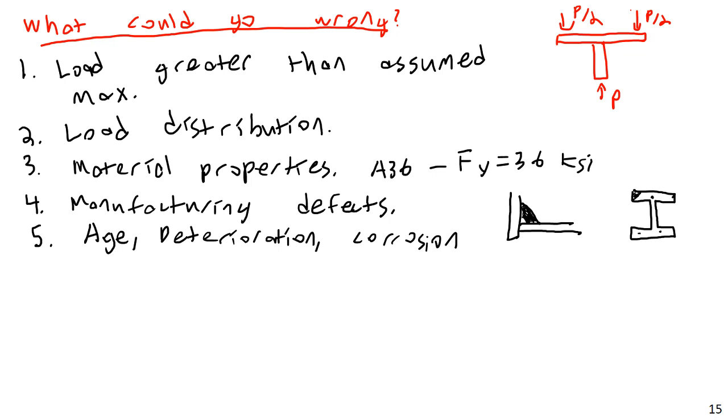So the way you often handle this in certain applications is, when designing things for corrosive environments, you'll actually assume a sort of corrosion case, where you will make sure your structure is still sound even if it's lost, say, the outer 1/16 of an inch of its surface due to corrosion. Now that's probably excessive for this sort of thing, but if I design my structure to the maximum limits right from the very beginning, then any kind of corrosion or even damage could be a problem. This damage could be chemical, like corrosion, or it could be physical.